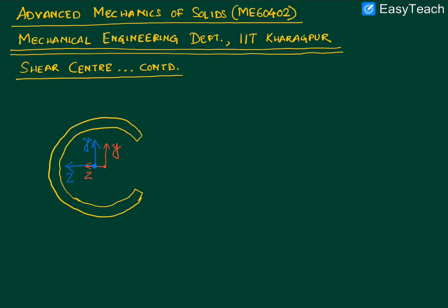So to resolve this confusion about the axis, what I'll do is I'll first of all write down the expression of the shear stress distribution, referred to the blue colored y and z axis such that the origin is actually located at the centroid of this particular cross section. So let me make this clear, that this thing is the centroid.